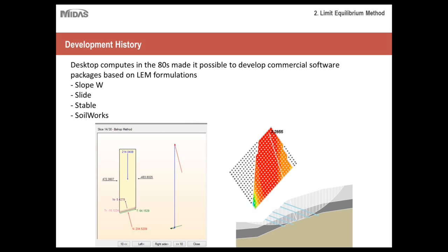It's very efficient. It's very easy to use. And just using these programs, they can easily calculate multiple arc surfaces or slip surfaces. They can automatically compute all the forces that are acting on each slice. And most programs will actually isolate your minimum factor of safety for you. So it's very convenient.